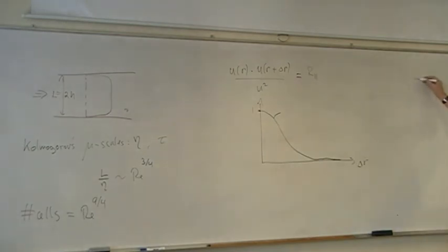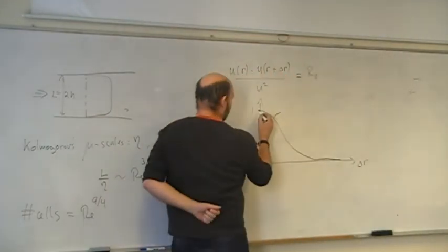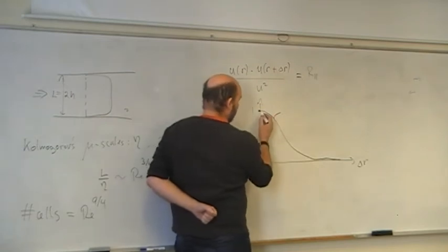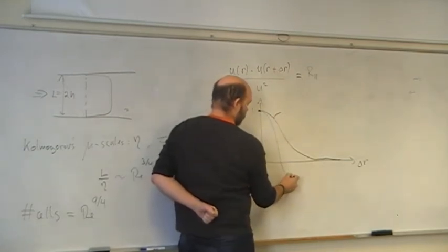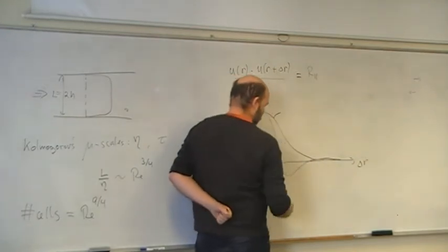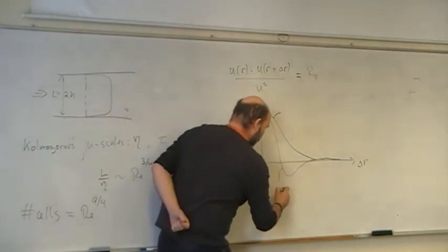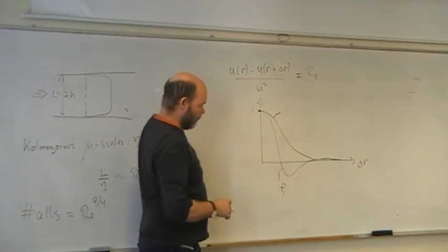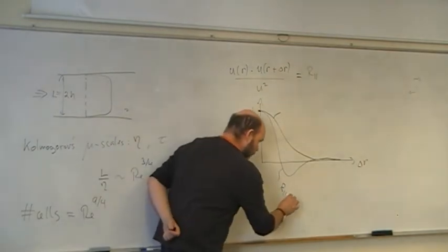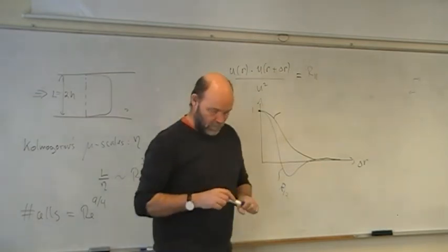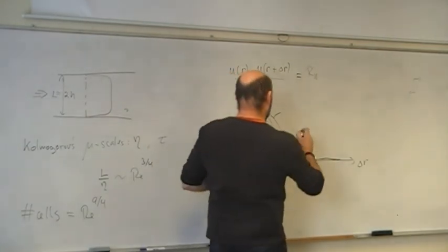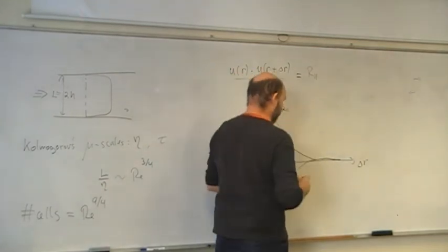If you go the other way, meaning you look at one velocity here and then you go in the y direction and see how it correlates to a velocity at a delta y distance, you will typically go something like this. Start with 1, then it will go negative and finally level off, and maybe even make some wavy motions. So this one will now be R1, it's the u velocity I'm looking at, but I go in the y direction. And this one will now be called R11.